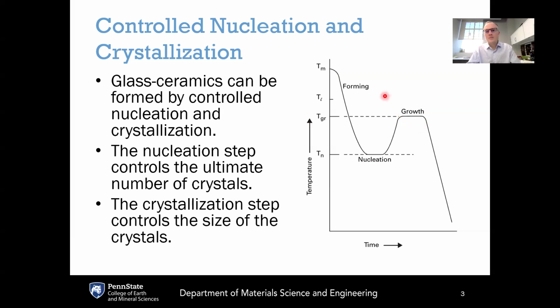Now, one of the major advantages of glass ceramics compared to traditional ceramics is the ease of forming glass ceramics. Traditional ceramics are usually made via a powder sintering route, where you take powders of the material and then they need to be pressed into a green body. That green body has a lot of porosity in it, and the goal then is to eliminate as much of that porosity as possible by having this porous green body undergo a sintering process. That sintering process involves applying high temperature, sometimes also higher or elevated pressure, in order to evolve the microstructure of the ceramic to eliminate the porosity.